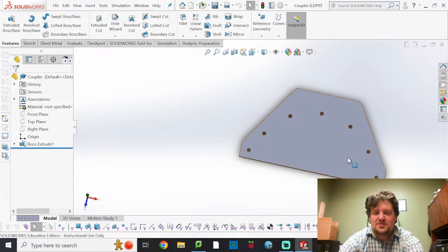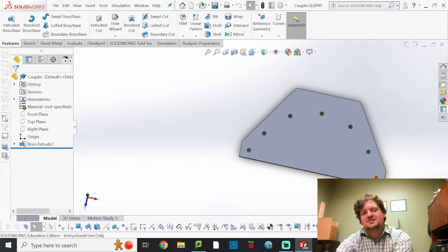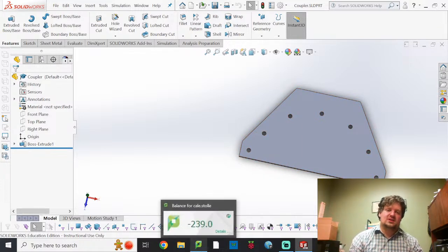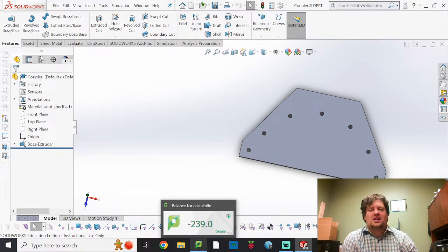So here, this is the coupler that I had. The input linkage was right here, the output linkage was right here. Now in this case, there's only 2 joints. In a static analysis, in a 2-joint system, if you do your sum of the forces in the x and y directions and your sum of the moments, what you end up finding is that this force and this force have to be equal and opposite because there's only 2 connections. In order for it to be in static equilibrium, there can't be a moment because the simple pin connections that allow rotation cannot carry a moment themselves.